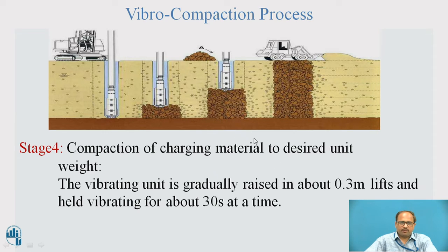In the fourth step, compaction of the charging material to the desired unit weight. The vibrating unit is gradually raised. First, you observe here this is an entire empty borehole. Then in the second step, we will add some granular materials through this vibrating jet.